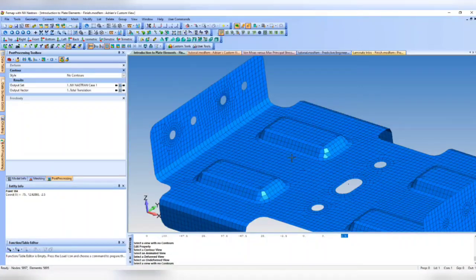So the cleaner the mesh, the more time it takes to create. If you just tell the software, hey, mesh this without cleaning up your geometry, it's going to include trias, because based off your structure, the system is just going to want to fit in trias because it's easier than trying to make it all quads.